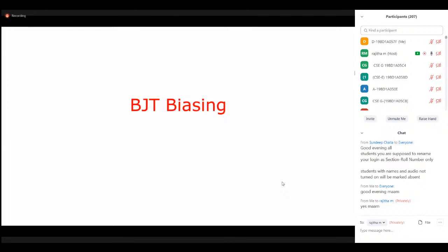Now, the cutoff region. How do we place the transistor in the cutoff region? I don't want to transfer any charge carriers from the emitter terminal to the collector terminal. So in order not to transfer any charge carriers from the emitter region to the collector region, we apply reverse bias to both junctions.